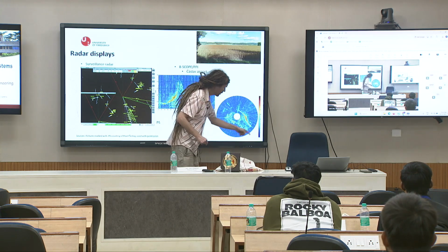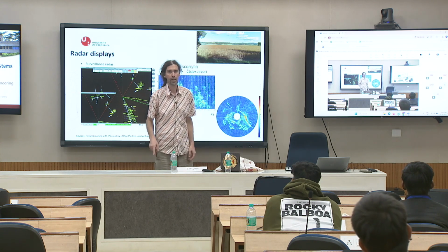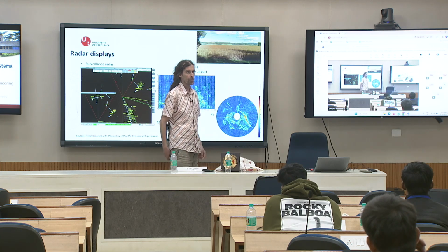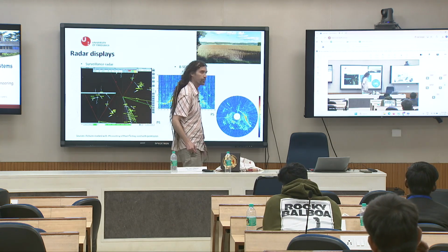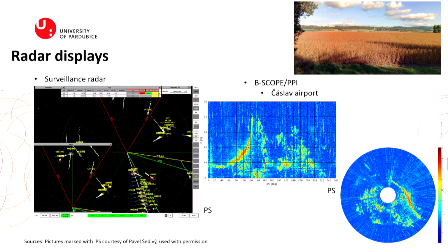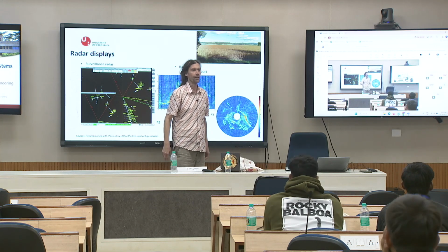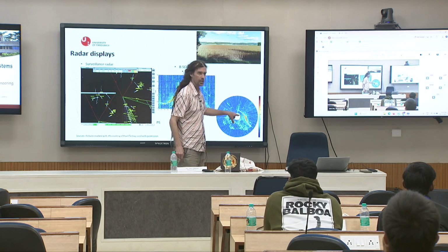And what is this maximum? It is the maximum range of your radar, and there you can't see. So if we have a radar up to 450 kilometers, like this weather radar, this will be 450 kilometers. And the blind zone will be, I don't know, 3 kilometers, something like this example. But I'm guessing, because of course you need to put it into the equation and compute, but just imagine. So radar can never detect anything that is in the blind zone.